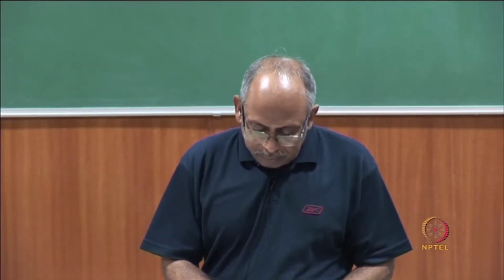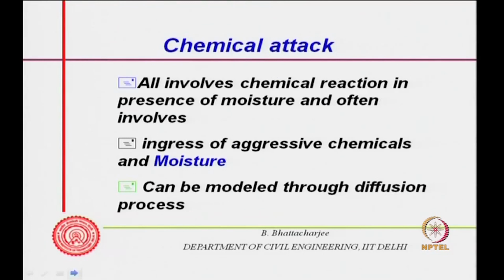But one important thing: there are many deterioration processes, but all actually involve chemical reactions, and most often the presence of moisture is an absolute must for most of these reactions to occur. Very rarely does dry concrete get affected by anything. So, it is very important that we keep this out. If you keep this out of the concrete system, then its durability will be infinite, right.